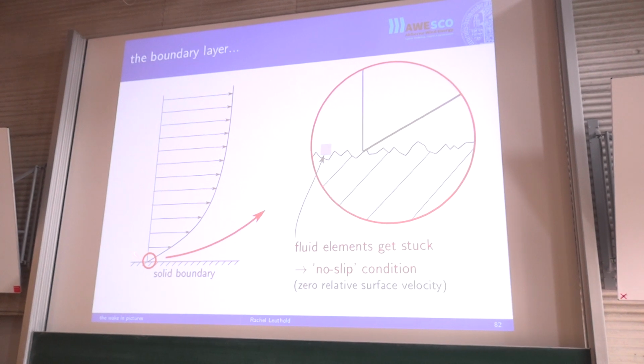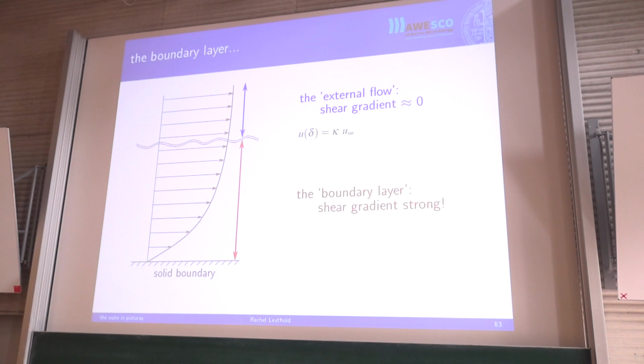And this then gives us the nice form, with some viscous help, of the velocity profile at the boundary layer. Anyway, what we might do is say we don't really care so much what this thing looks like, as we do care that at some arbitrary height, which we're going to call delta, the boundary layer thickness, we've effectively reached the free stream velocity. So at delta, we have more or less 90% or 95% or 99%, for example, of the free stream velocity.